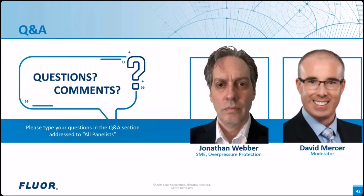But it can be done, but I would caution that it's only used as a last resort because it becomes very, very complicated. Proving the functionality with the very high-speed waves is very complex and requires very specialized assessment. So I tend to prefer to avoid HIPPS on liquid pack systems where possible.